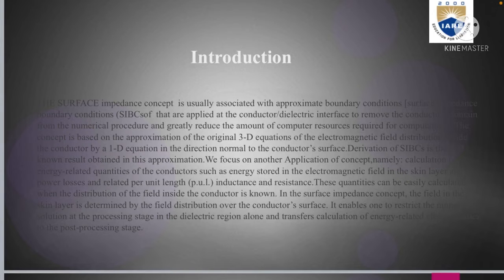In the surface impedance concept, the field in the skin layer is determined by the field distribution over the conductor's surface. It enables one to restrict the numerical solutions at the processing stage to the dielectric region along the transverse, with calculation of energy related characteristics at the post processing stage.